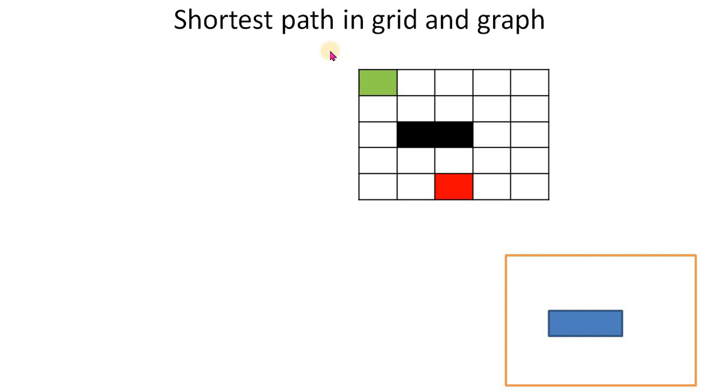So the goal of path planning, as we have seen in the previous lectures, is this. Let's say this is the start location we have, and this is the obstacle, this is the target location, and this whole area is our environment, or the C space, or the configuration space. This is a space where a robot can move around, and the white cells represent the free space. The robot can move here. The black cells mean there is an obstacle, so the robot is not allowed to go there. And it's clear from this picture that this is a discrete map, because we have divided the whole C space into cells, or you can say a grid. So this is also a grid-based map.